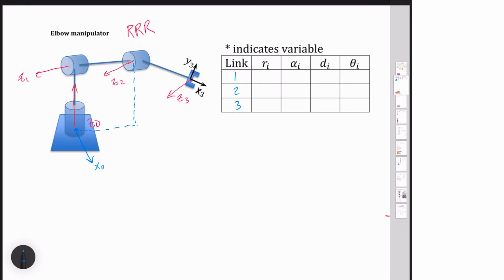So now let's draw in I've got my Z1 here, and I want to find my origin for my Z1 frame. And so I've got my Z0 coming over here and my Z1 coming in here. They intersect at some point, and that intersection has to be my origin, O1. And then what I do is I extend that line.